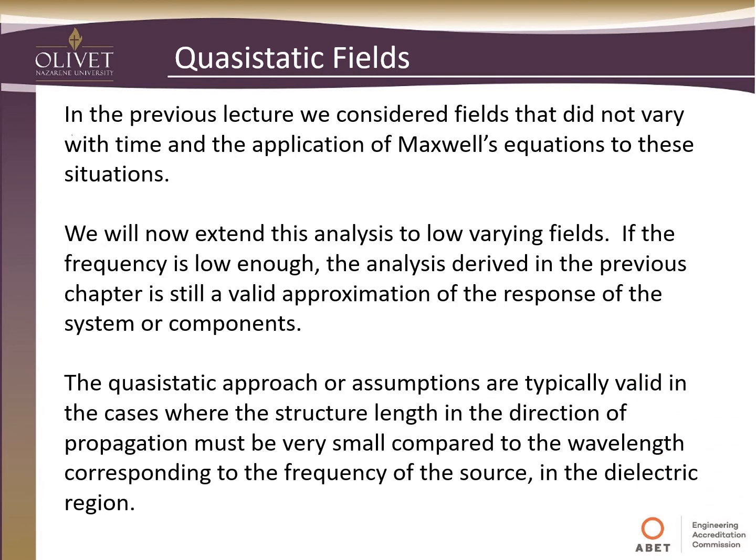The quasi-static approach or assumptions are typically valid in the cases where the structure length in the direction of propagation is very small compared to the wavelength corresponding to the frequency of the source in the dielectric. So if you get to the case where your device is 40, 50, 60 cycles in length, then these don't apply. But if it's a half a cycle, or a quarter of a cycle in length of the wavelength of your frequency, then these would probably hold.